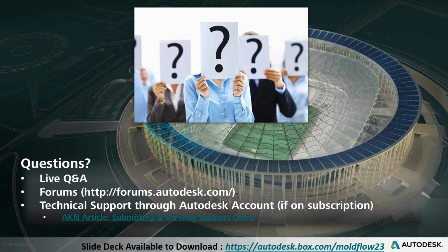Sure. So I do see one question here. Looks like someone has a situation using the 3D mesh where coarser mesh over predicted warp by about 5 times. So I think this circles back to what Kristen spoke about, needing to review the quality of your mesh, and if you are identifying it as a more coarse mesh, and with the finer mesh you're getting more accurate warpage results, I wouldn't really compare one mesh type to the other. I would go with your finer meshed value there. Anything to add to that, Kristen?